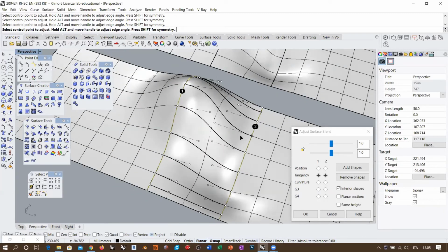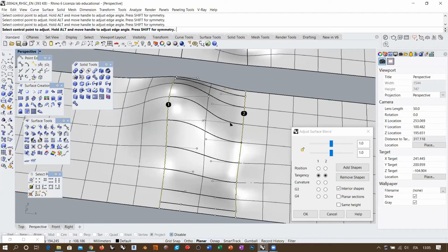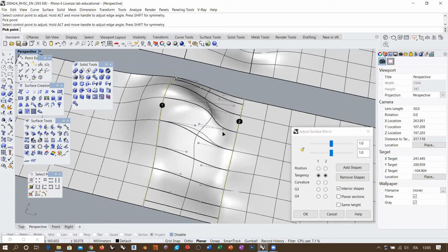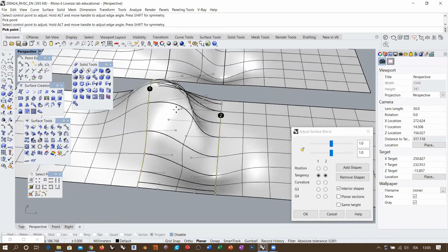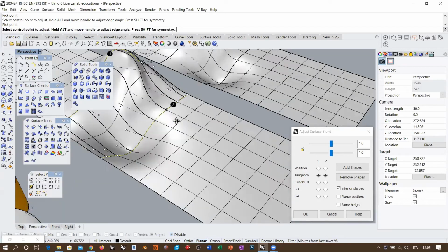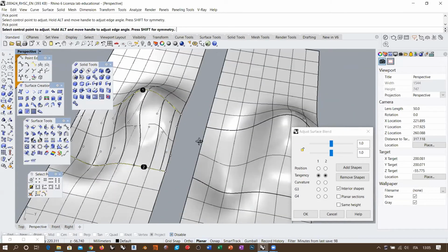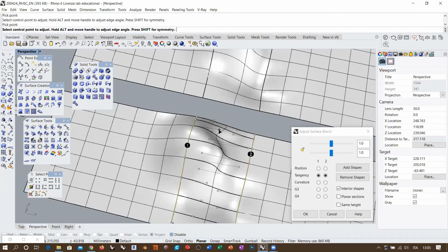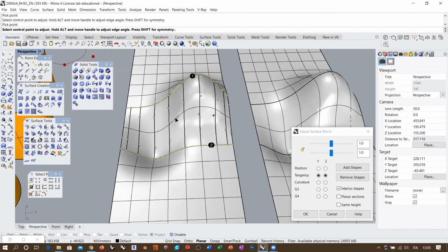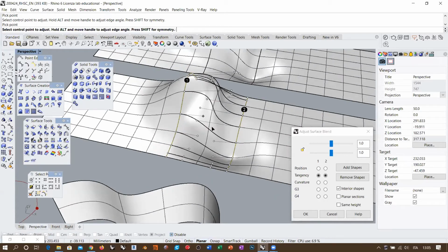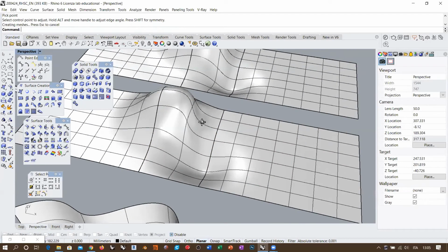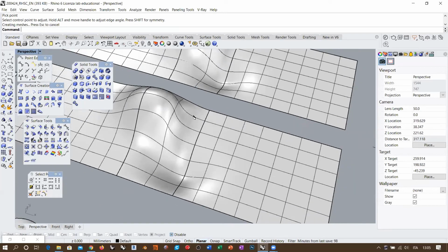So if you have this, you have access to a whole range of blend surfaces, because you can simply change the shape of one section at a time, and you can create a different blend surface, also extreme blend surfaces, like, I don't know, this kind of wavy thing here, okay? But anyway, you shape the surface as you please, because you know that you are working with a degree 3 surface, and you get the preliminary result, okay? Now you want curvature continuity.